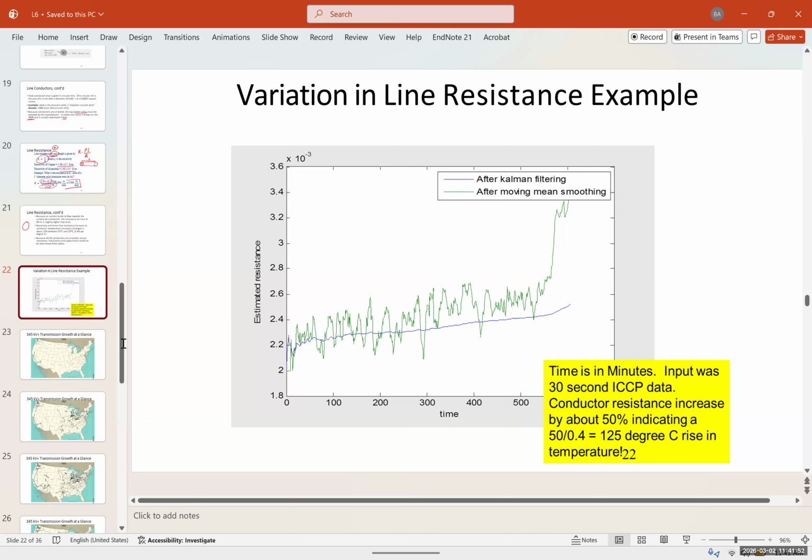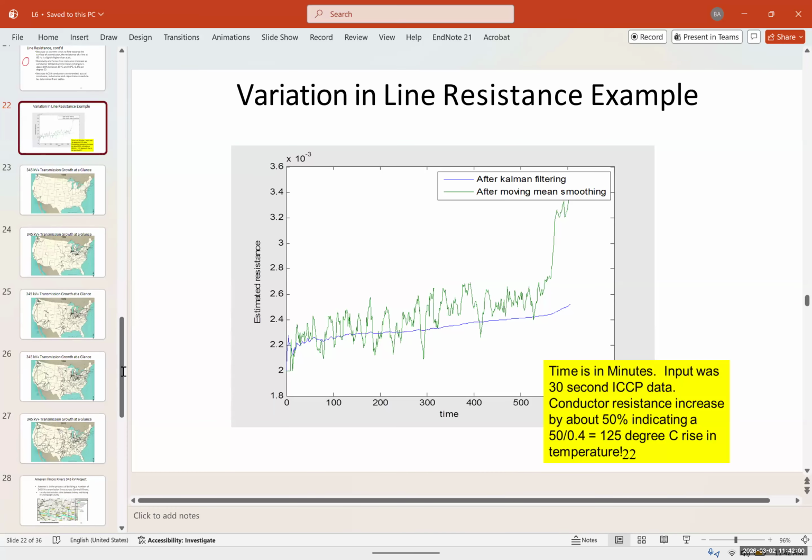You can see it suddenly shoots up when you have higher temperatures. And after that you have sagging, it gets very soft, and you're going to have a lot of problems. I already showed you the problems that sagging may have. It's basically melting your wire.